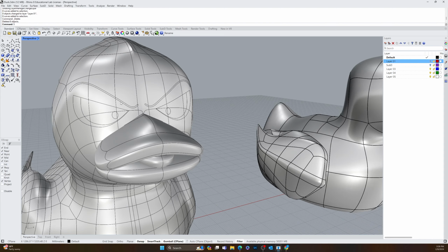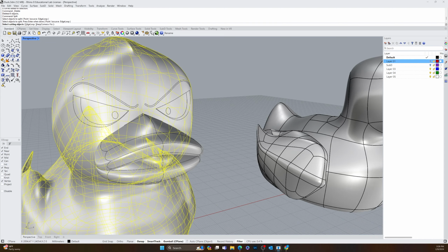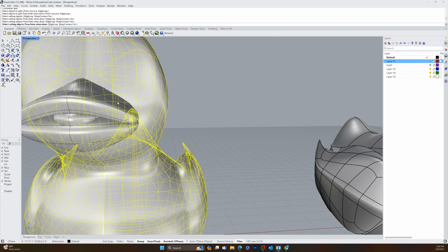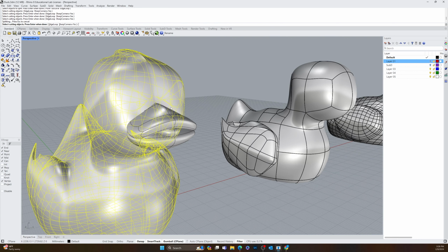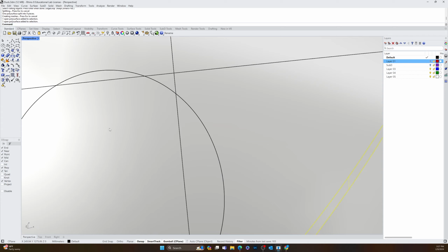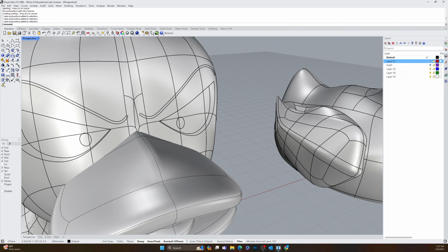So split this object, enter, with this one. Oops. Split this object, enter, with that, and left to right select that. Control shift or control click if you accidentally grab anything. Yeah, there we go. And then enter. Okay, so that now splits these into individual little sections